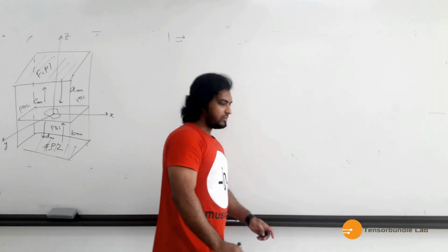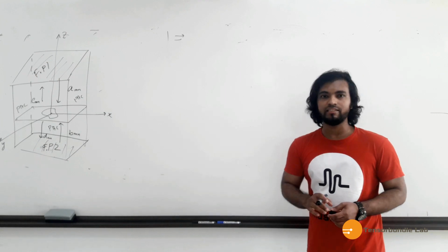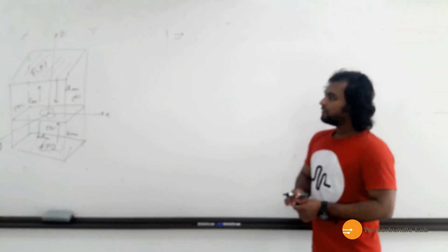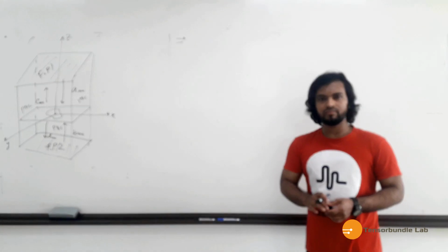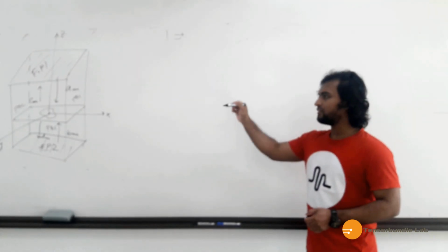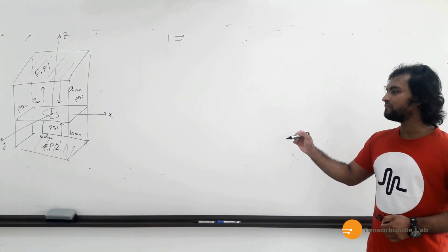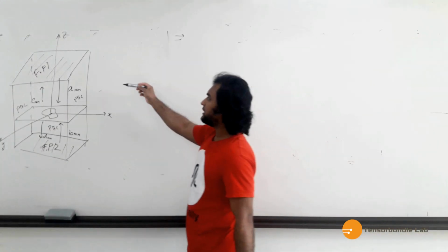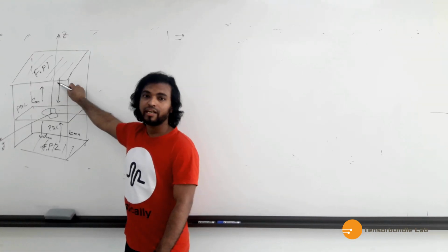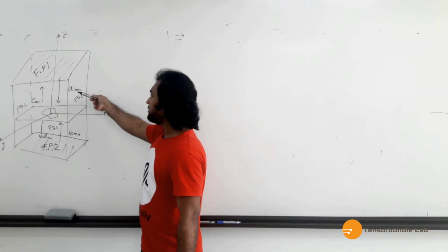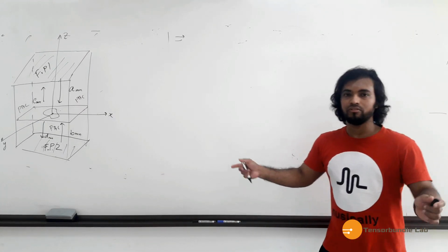Now, every device in microwave engineering can be characterized by a scattering matrix. So our next goal is to determine a scattering matrix that can contain all the information of the Floquet modes and angles of incidence, because the response will also depend on the angle of incidence. The angle with which the waves hit the structure will determine the response of the overall system.